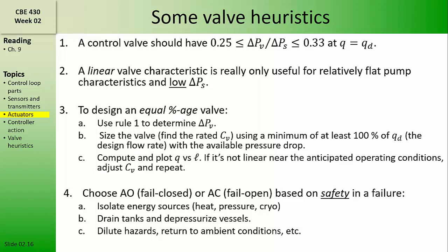Depending on whether we've chosen a valve that fails open or fails closed, we'll want to select a controller that sends a signal that either increases or decreases to open the valve. That behavior is referred to as the controller action, and we'll talk about that in the next video.